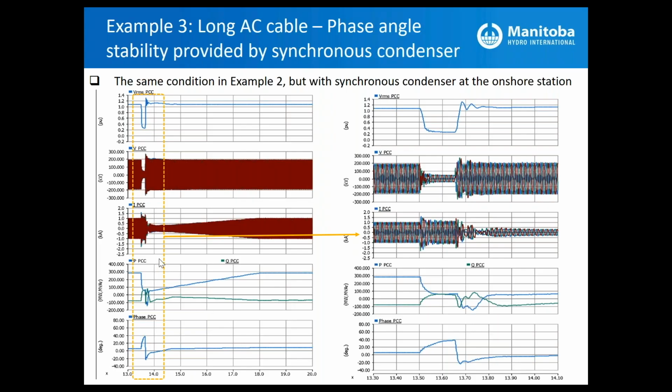With a synchronous condenser, sometimes you actually need higher than typical inertial levels, like with heavier rotors or added flywheels, to increase the typical inertia constants of synchronous condensers, which in normal conditions are not meant for providing inertia, but rather for providing higher short circuit levels or maintaining voltage. Here you need the additional inertia to stabilize the phase angle.